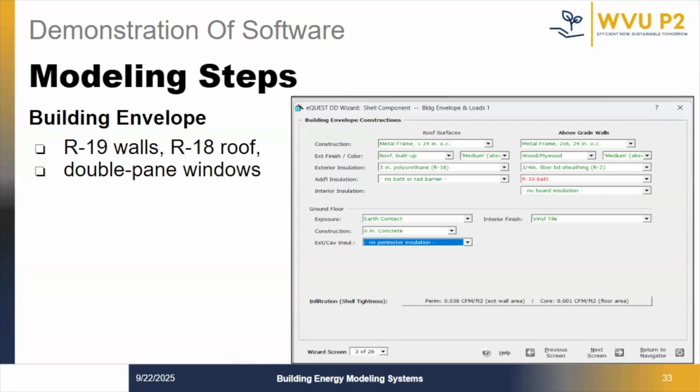The table typically lists exact material layers like exterior cladding, insulation types, and vapor barriers to ensure accurate heat flow calculation. For example, a 20% improvement in envelope performance could reduce the building's HVAC energy use by 15-30%, highlighting why these details matter. Always validate input against climate-specific standards like ASHRAE 90.1.